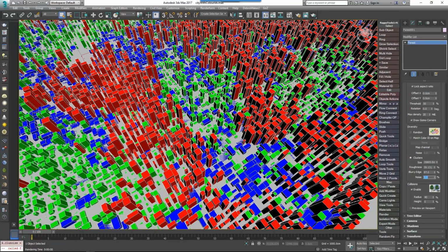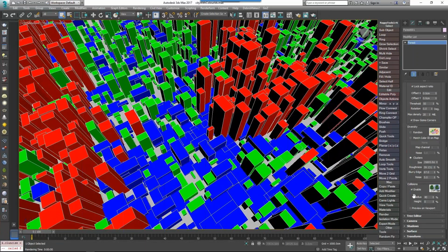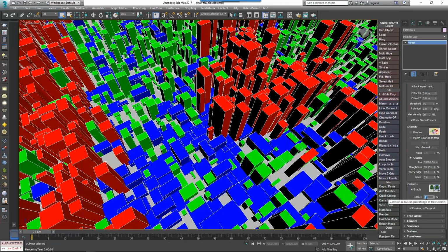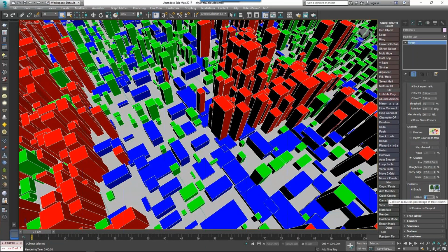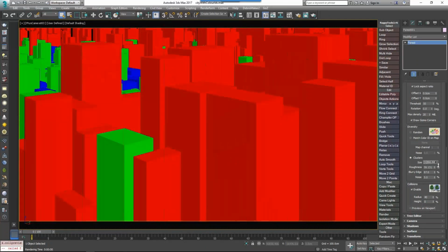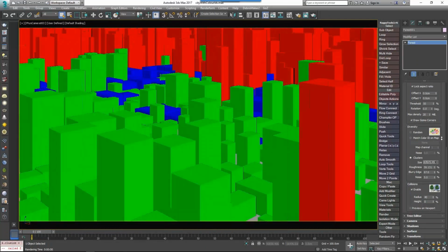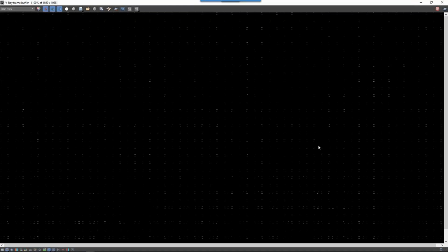And then another thing is the buildings, we don't generally want them to collide visibly. So we have this collisions option too. And Forest Pack creates a spherical collision volume around each object based on the bounding box size. And you can use that to make sure that buildings, or minimize the amount that these buildings intersect. And you can change those properties from this rollout as well. And then once you've done that, you can just sort of change the clusters around till you get a good view from the viewport, hit render, and you're good to go.